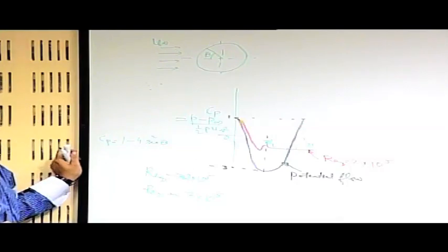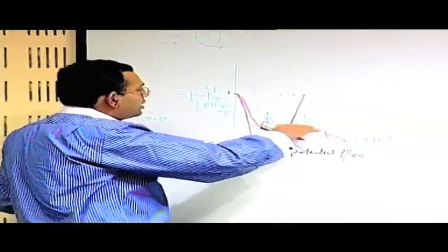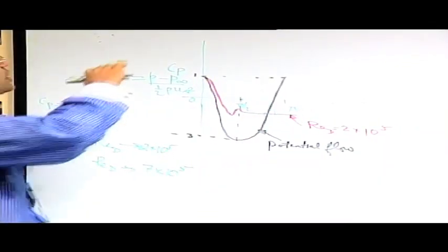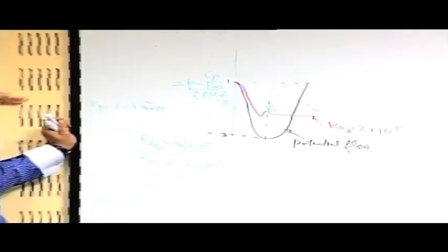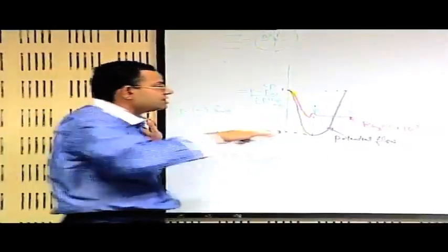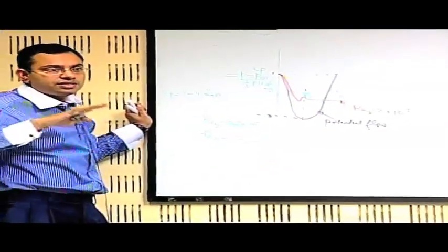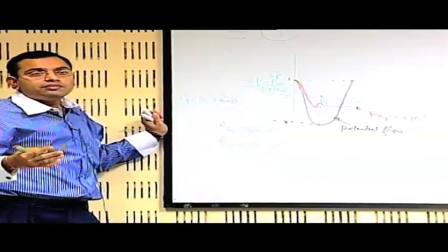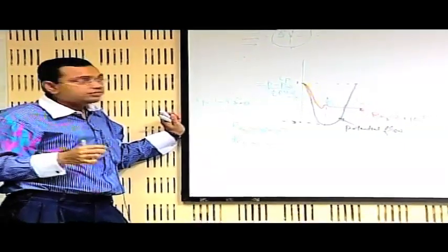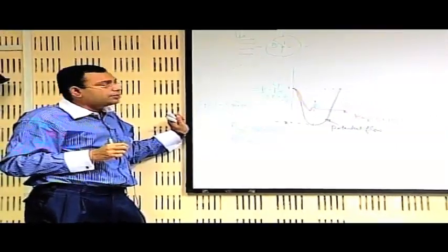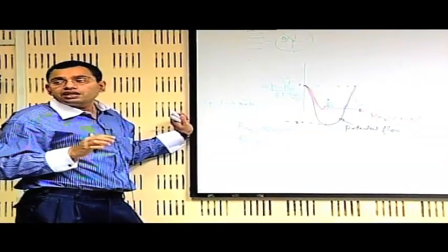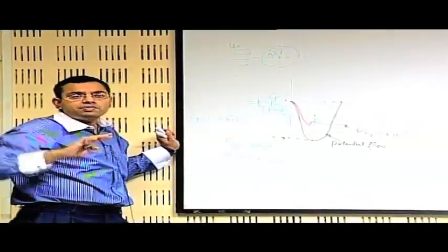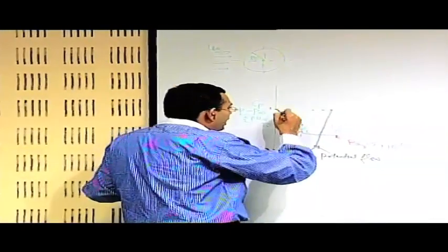See, after the separation has occurred, the Cp is roughly a constant. That means the pressure in the low pressure region or the wake region, after which the boundary layer separation has occurred, is almost like a uniform pressure which does not change further with theta, and it is typically a low pressure region. When it is 7 into 10 to the power 5, say it is beyond the critical limit or the threshold limit. So then the separation will be further delayed, and typically this separation may occur close to 120 degree or something like that, maybe 118 degree, this type of angle, and till that limit.